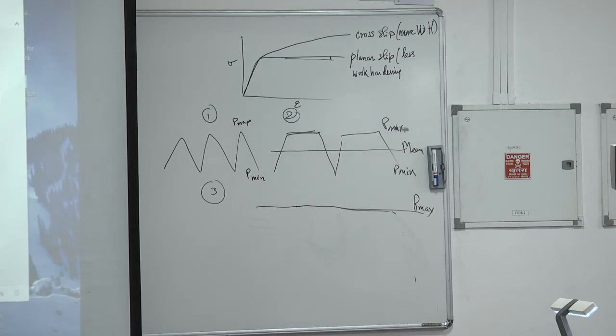Striations are not found in the case of constant amplitude loading. There is no striation found in the picture. Striations, beach marks? You won't see beach marks at this level, in the scanning electron microscope. Beach marks are usually at much lower magnification, maybe 50x. So you won't see beach marks here. You'll see more striations. Good point.